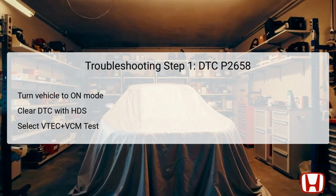In the first troubleshooting step for DTC P2658, the technician must first turn the vehicle to the on mode, which activates the electrical systems. The next critical action is to clear the DTC using the Honda Diagnostics System, HDS, a powerful tool that provides insights into the vehicle's performance. By resetting the DTC, the technician can ensure that any intermittent faults are addressed, and gives a clean slate for diagnostic testing.